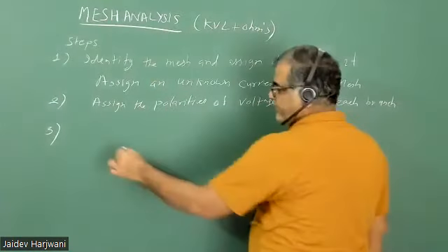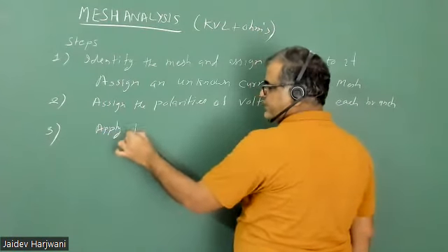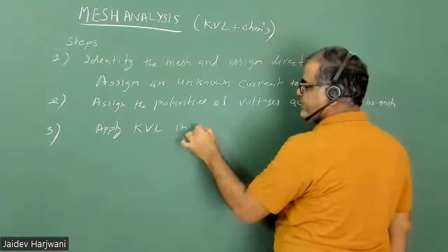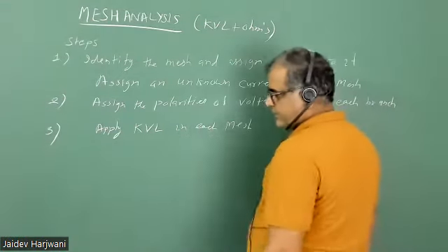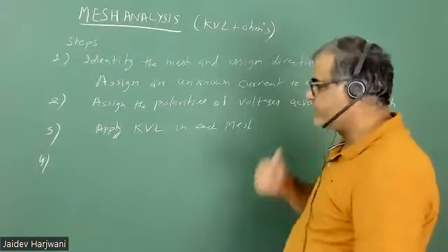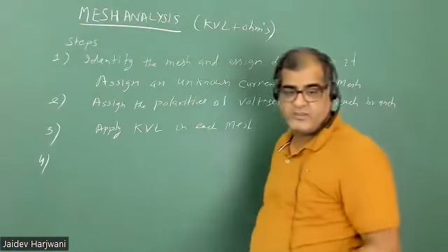Okay, apply KVL in each mesh. Once you know the polarities, now you can apply the KVL in each mesh. Okay, and then depending on the number of meshes, if 2 meshes, you get 2 equations. So solve the simultaneous equations. Yes.